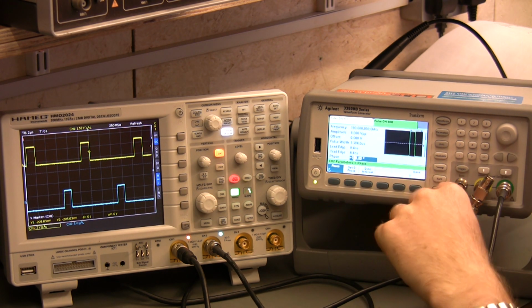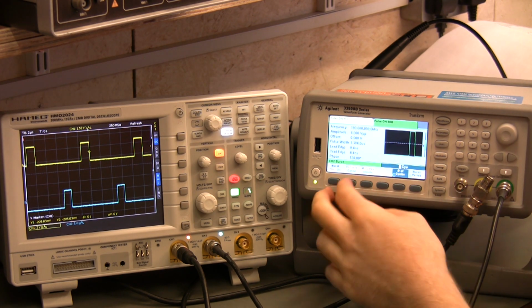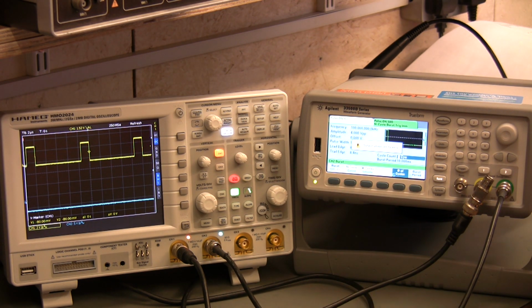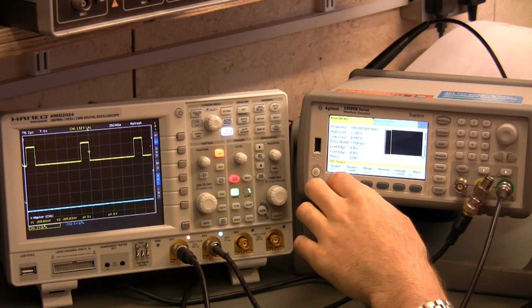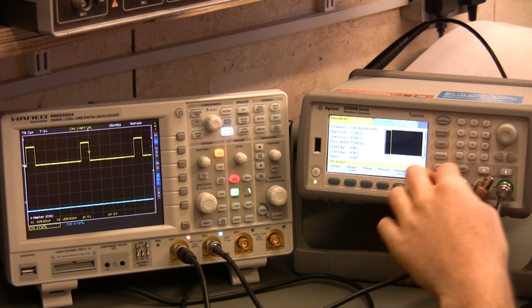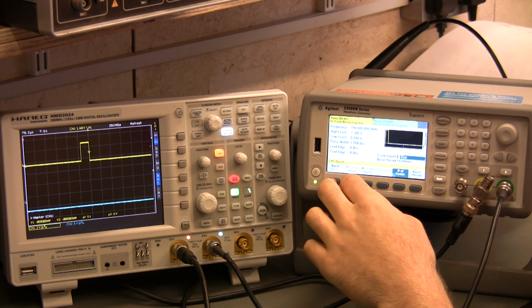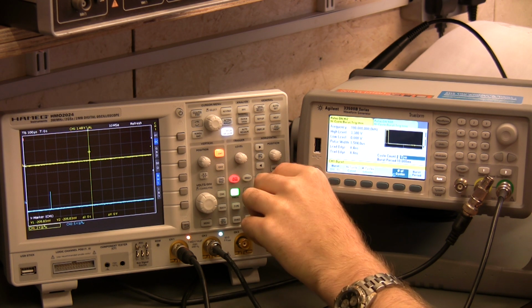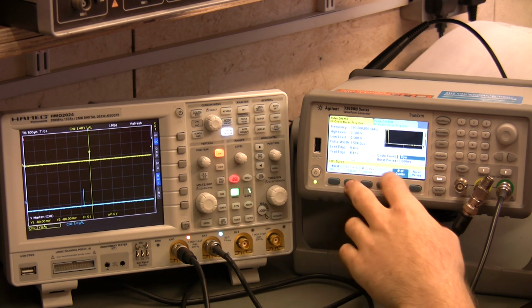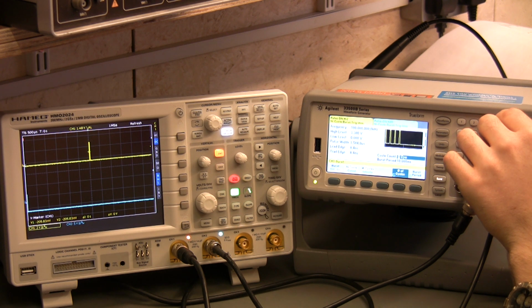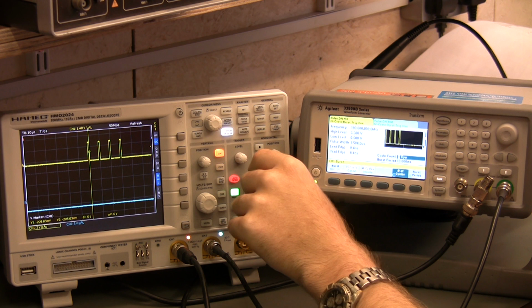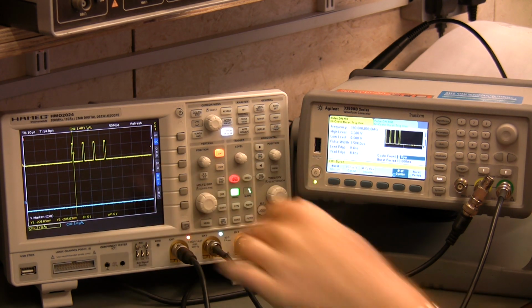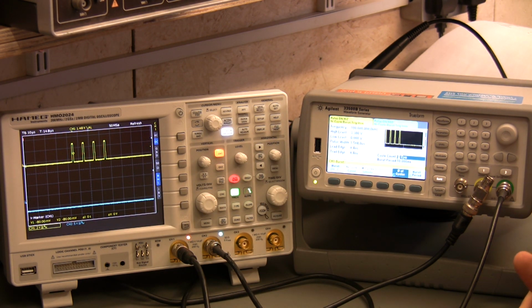And also, if you combine this with something like the burst functionality, or what should we do? Let's do this on channel 1, shall we? Burst on for n number of cycles. How many cycles? Let's do a 4 pulse burst. Okay, and that's basically most of the functionality you do have in a normal pulse generator.